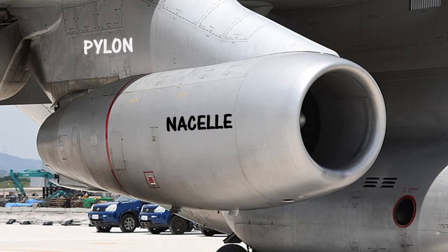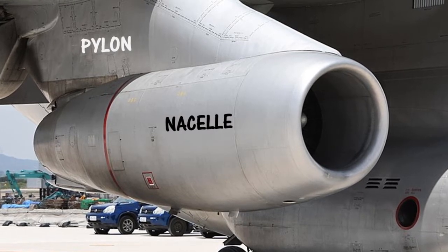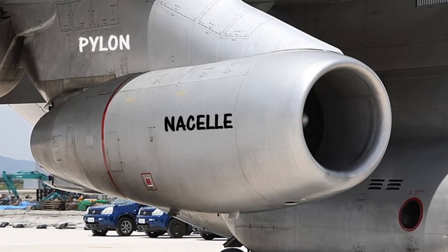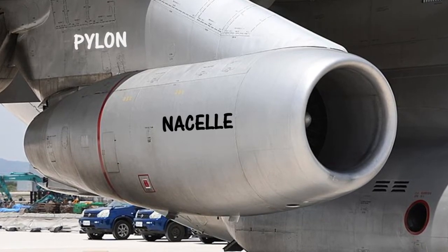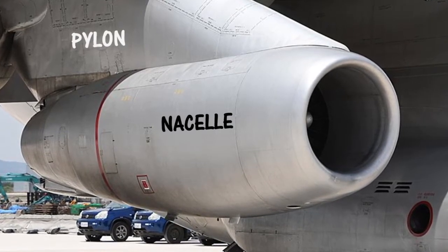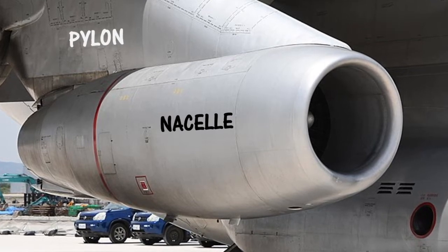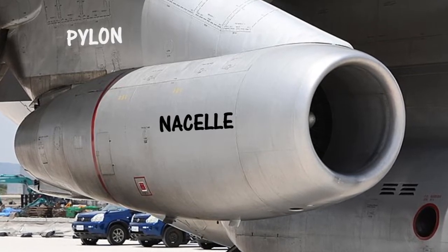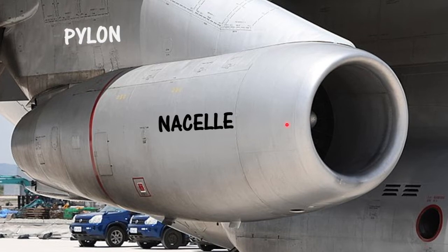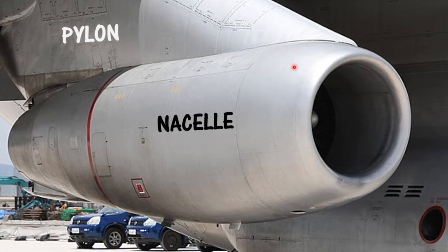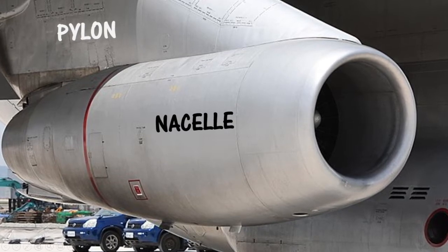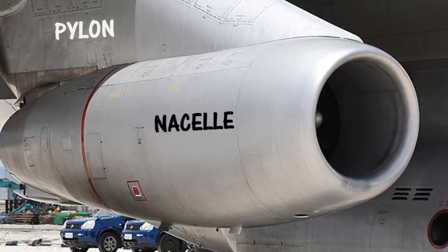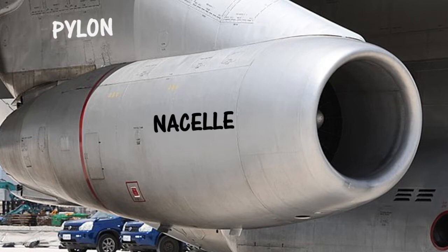Propulsion systems integration within the aircraft takes into consideration avionics, an interface with engine computers, propulsion system cockpit controls, and propulsion system displays and warnings. The nacelle and its design considerations are aerodynamics, air conducting through and around the engine, acoustic attenuation, ventilation, thrust reverser, which is an engine mechanism to decelerate during touchdown, and anti-icing system to protect the engine.